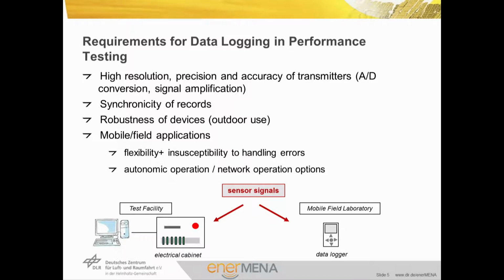The resolution in time is chosen according to expected dynamics of the system under test. Typical values for logging intervals lie in the range of several seconds. In terms of the signals themselves, 4 to 20 mA signals are preferred for analog signals. Besides, the transmission lines should be kept as short as possible.